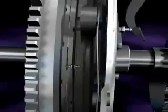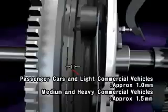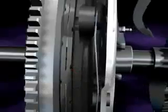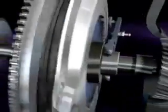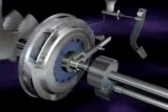The clearance between the clutch disc and pressure plate when disengaged is approximately 1 millimeter for passenger cars and light commercial vehicles, and 1.5 millimeters for medium and heavy commercial vehicles. This engagement and disengagement is the basic principle of a manual clutch.